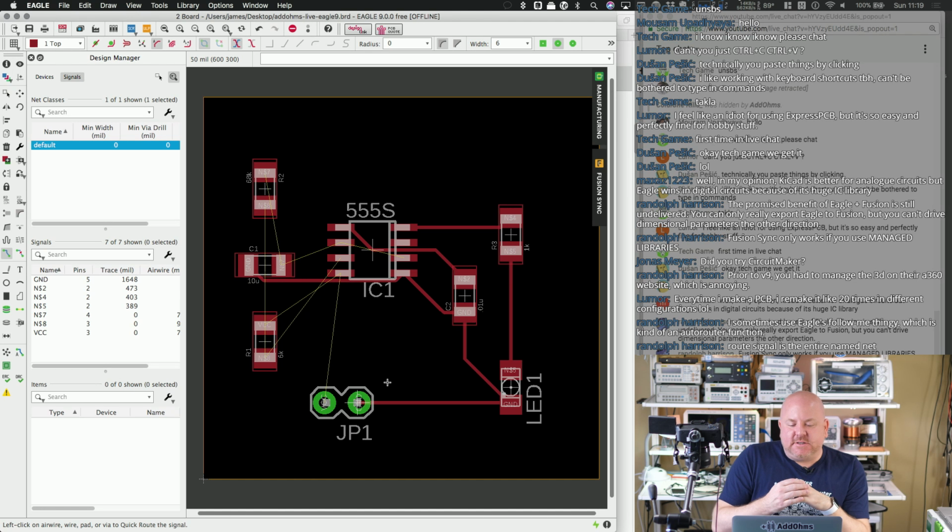I can actually see a really good use for that one. If we go back to the Pyramidino design that I was doing, if you remember that episode, I did VCC last. To me, that's the least critical route, since there's a ground plane for ground. All of the signal traces were done, and VCC pins have decoupling capacitors, so they can tolerate a few more twists and turns in the traces. Now, if there was a critical power route, then yeah, I'd do that one first. But I could see doing debug signals, or I guess those would be individual signals. I see some value in, I just don't care about these, so just route them. So that's kind of cool.